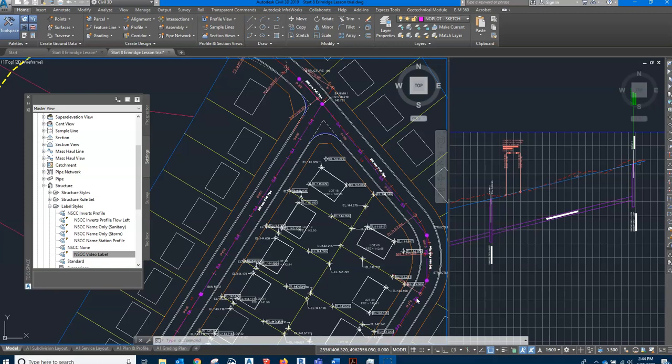So just to start with the basics here, with gravity pipes, of course, we must have a slope on the pipes. The functionality of those pipes is controlled by gravity to make the water or sewage flow, whereas in pressure pipe networks, we don't have to worry about the slope. But in both cases, we do have to worry about what kind of cover we have on the pipes.